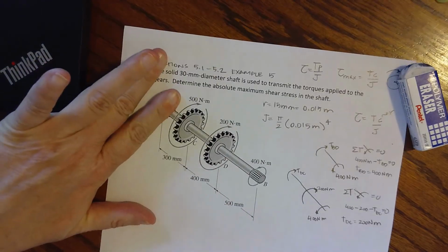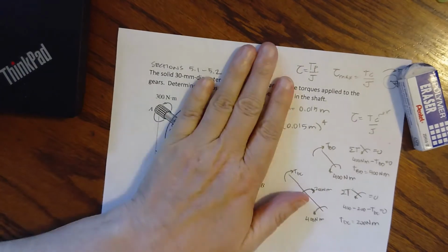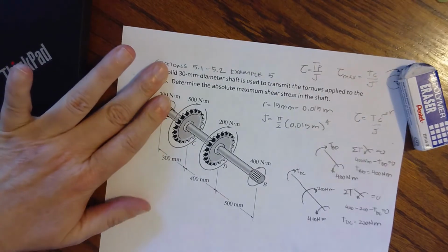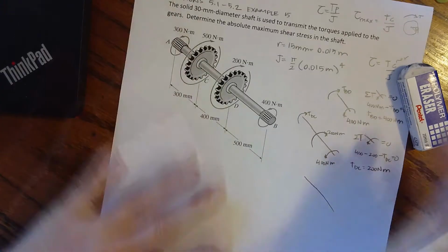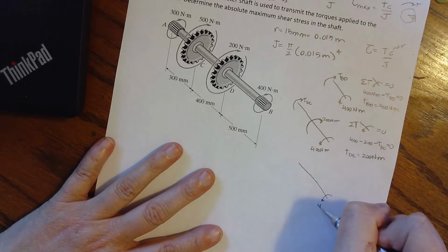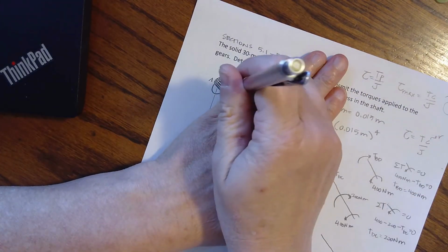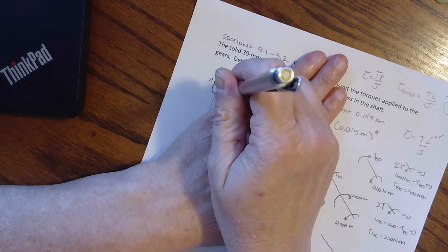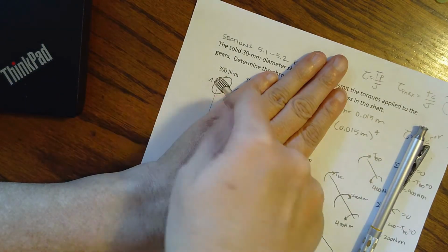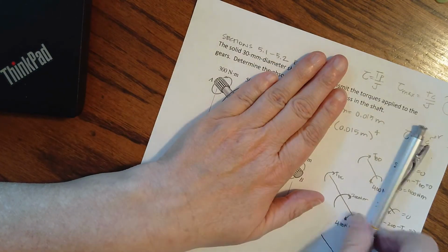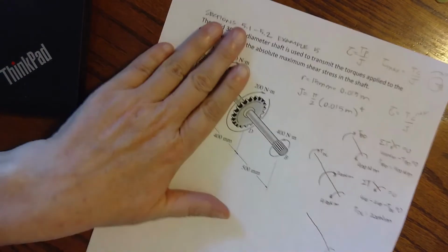So now we need to come back here, and we can go all the way back, or we could draw from the other end because that would be the shorter little piece, but let's just continue the way we've been doing this. And here's our free body diagram. I have 400 coming at me. I know it should end with 300. If I'm just looking at this part of the segment, it's got to be 300. This internal torque is going to be going toward it like this, which is negative. So I'm expecting a negative 300 for my torque. But anyways, let's just go forwards.